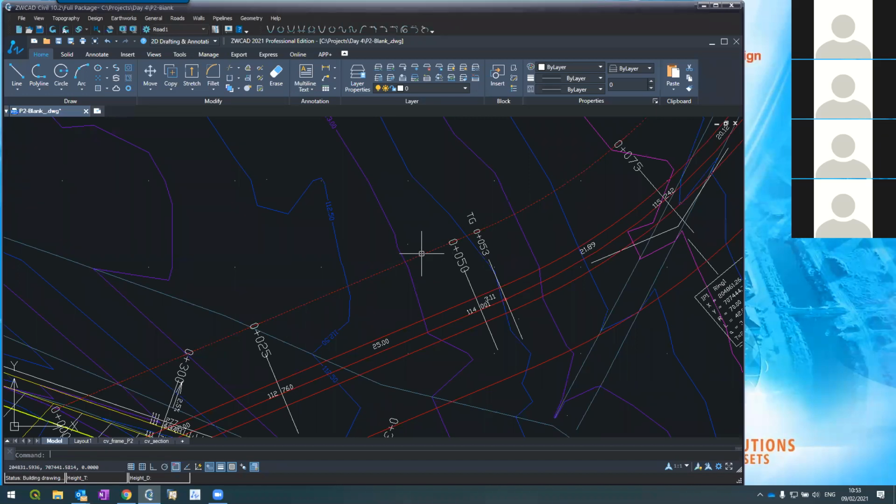Now, I'm using a sidewalk. Here I had shoulders. Here I want to do a sidewalk. The sidewalk to the left is 3.5 meters. Why? It's my decision. And to the right, only 1.5 meters. This is what I want. So this is my road geometry. From the center line, median till here and here, asphalt here and here, sidewalk here and here. Let me save it.